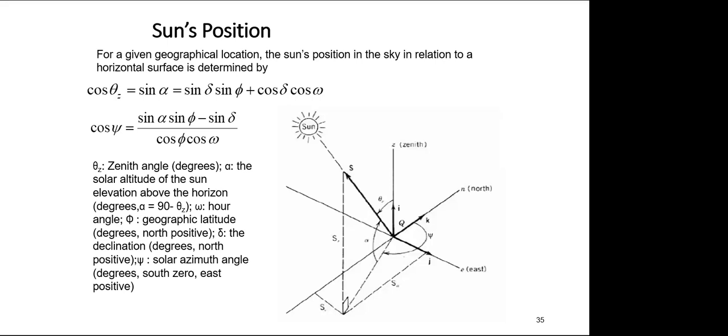Maybe you are aware of solar trackers, no? Some people are using the solar tracking concept. The sun can be tracked by solar panels so that a high amount of energy can be harnessed. If we can track the sun rather than using fixed mounted solar panels, that is a good opportunity, because sun position is important. Then how can we find out the sun position? There are different technologies used here, which I'll explain a little bit later. Especially for parabolic solar collectors, it is required to use the sun position. Otherwise, it cannot be focused onto the correct focal point.